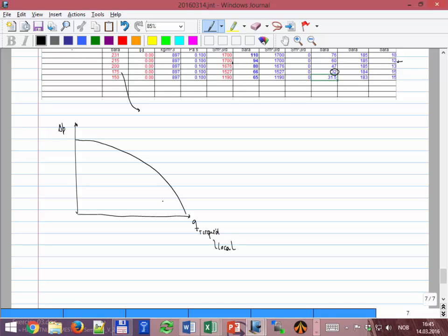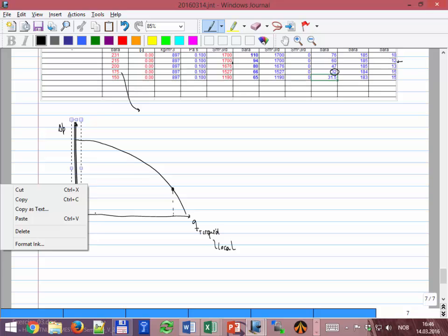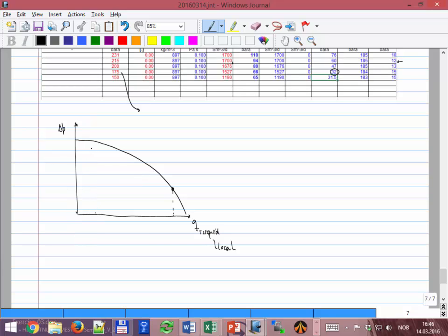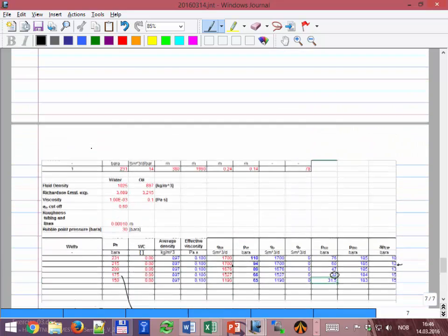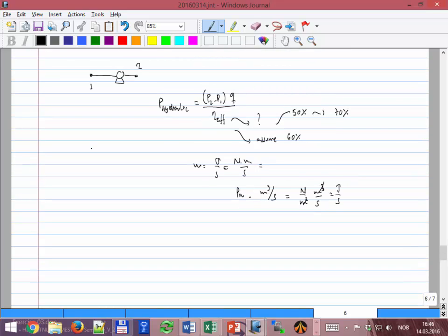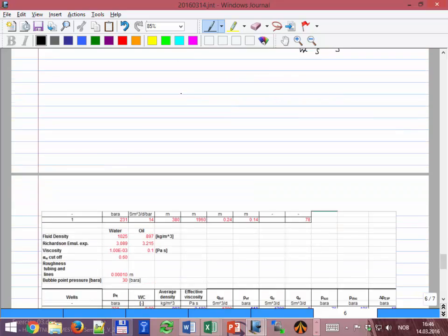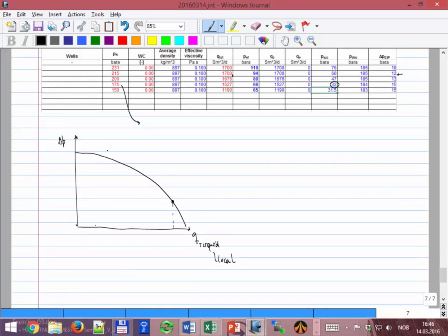And I told you that you can either produce a very high rate with a low delta P, or you can produce a low rate with a very high delta P. And if you see the power equation that we have done, that relationship comes given by that. If I increase this one, and this one is fixed, then this one has to go down. So really the line is giving you kind of the constant energy line. And this is for one rotational frequency.